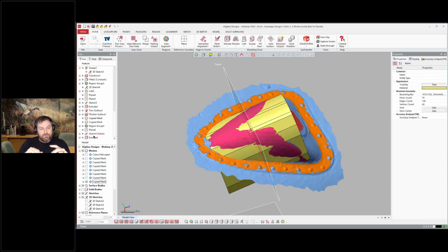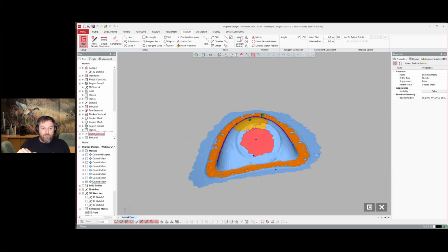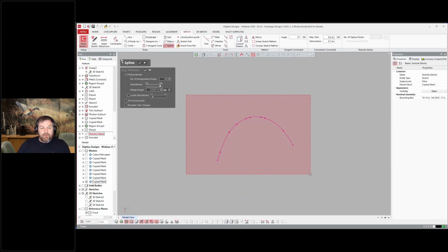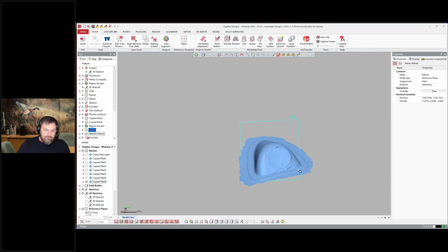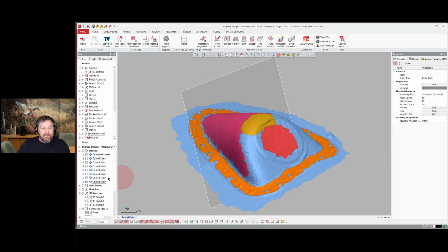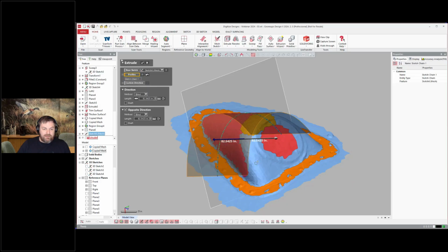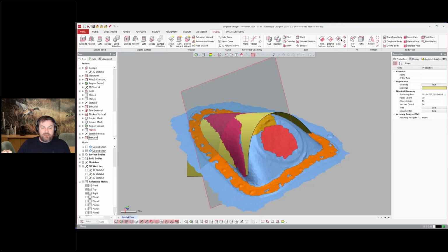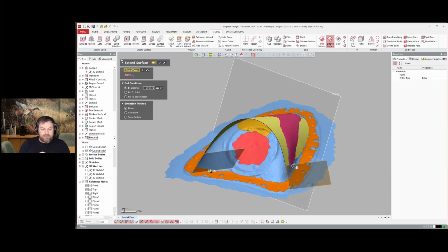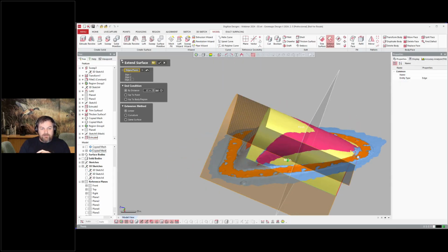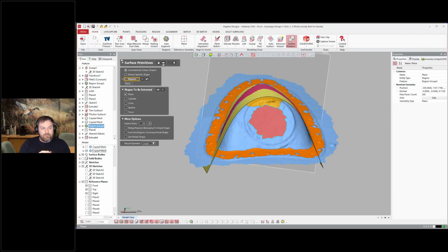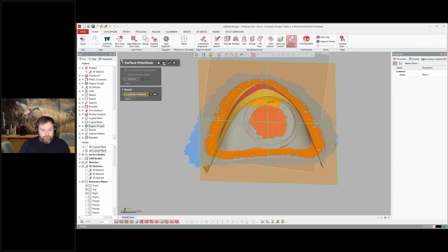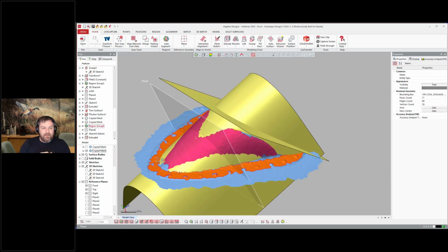Now here's another instance where I actually used the extrusion wizard, and it didn't give me exactly what I wanted. So the wizard did all the heavy work for me. What I went ahead and did is I let it give me what it gave me, and then I rebuilt that curve in like 2 minutes to create a nice clean curve. So even if a wizard doesn't give you exactly what you want, remember we were talking about this as a history-based CAD modeler, it still gives me the history to work with, the model that it gives me from those automatic tools, and then I'm able to work with them and create better geometry from there.